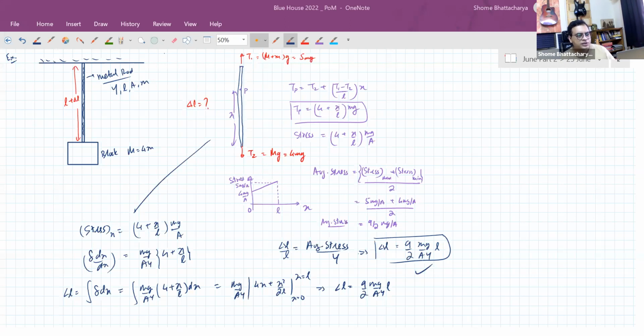Okay. All right, so I think with the examples we've done of fluid mechanics today, you should be well prepared for the test coming up on Sunday. Just make sure that you go through all the derivations, including one thing I noticed we did not cover in the doubts today, but it's very important, which is the case of pressure gradient in an accelerated tank. Just remember that formula tan theta is equal to a by g in case of horizontal acceleration, with horizontal pressure gradient coming because of pseudo force, along with vertical pressure gradient coming because of weight. Okay, so make sure you revise that portion from the notes very carefully, and I think you should be fine with fluid mechanics.